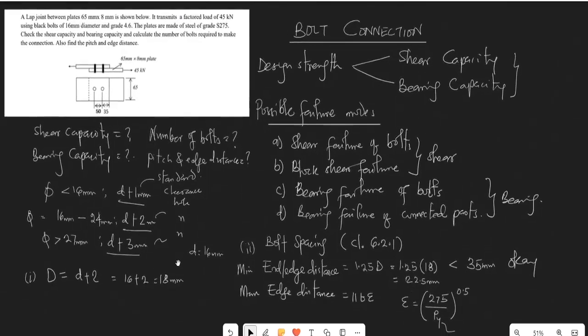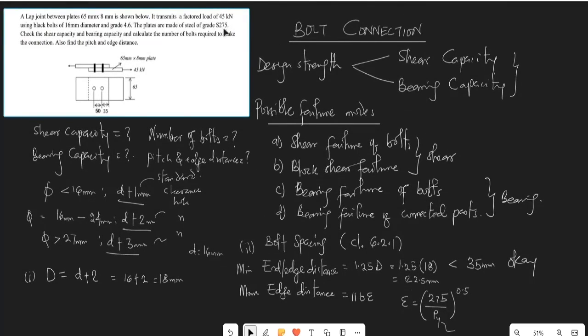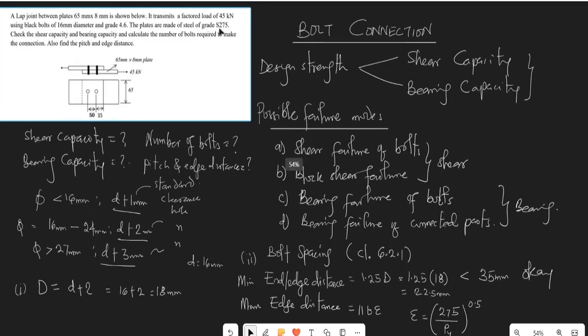So we have the plates made of steel grade S275. Of course, in S275 we have several strengths of steel. So we need to be sure of which to work with. You can't just pick 275 because they said grade S275. If you do that, you might not be so accurate, especially if the thickness of your plates does not fall in the category where 275 would apply. It's not guesswork, and that's why we have the code of practice to work with always. So I'll take you to where you can quietly confirm everything you're working with so that you'll be a little more accurate.